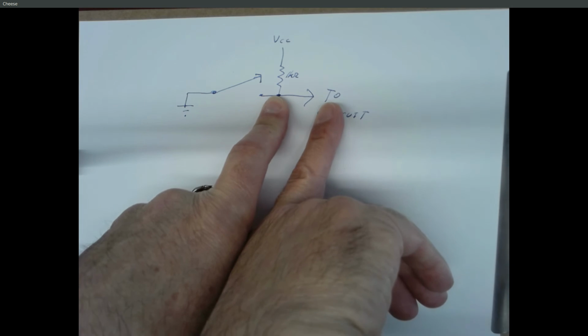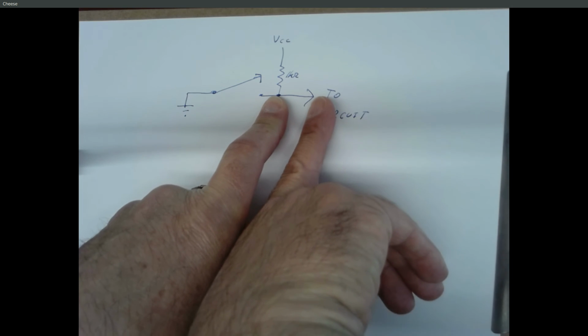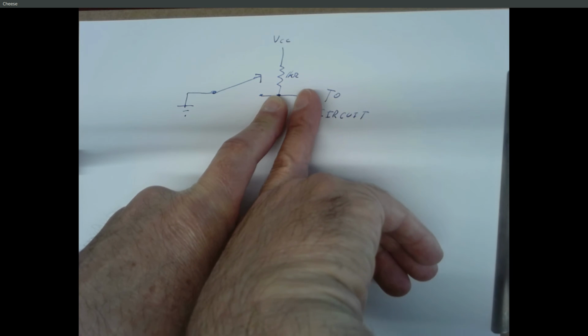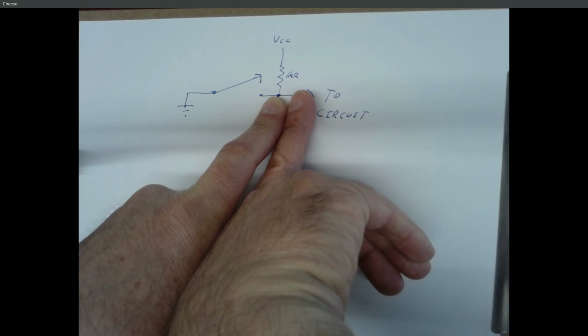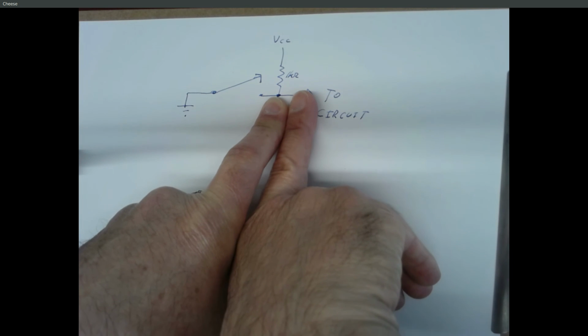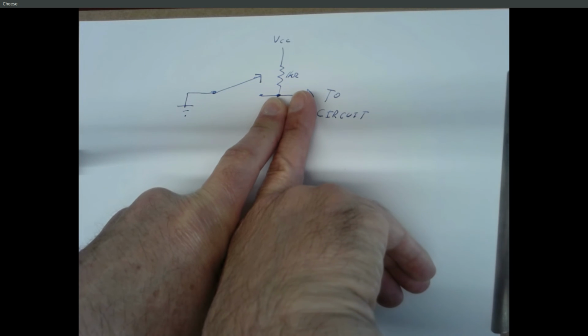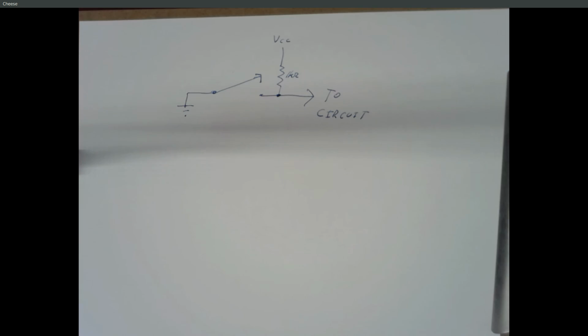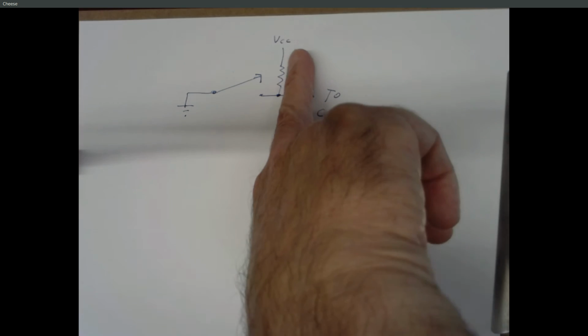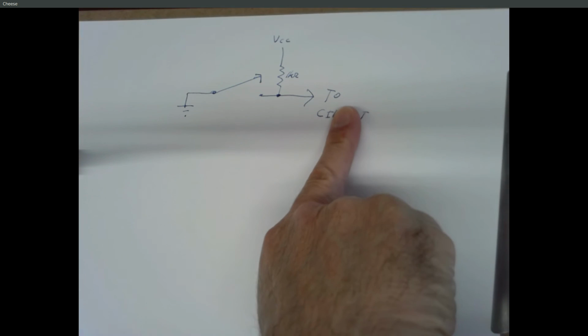For a 74LS04 chip, that's fine. For a PIC processor that you use in Engineering 270, that might damage the inputs eventually. For an Intel X-Scale processor that costs $100 or so, that will totally blow the input pin. And then you have to remember, don't use that input pin again because it doesn't work. So we always want a 1K resistor if we're putting 5 volts into a circuit.